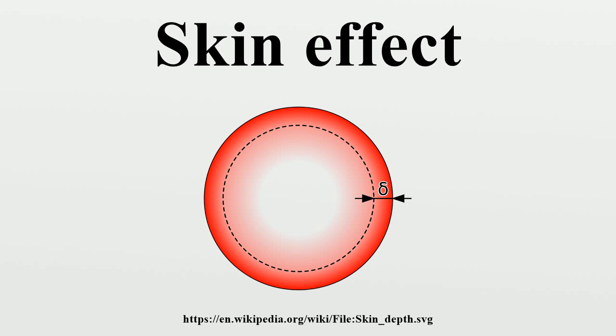The skin effect is due to opposing eddy currents induced by the changing magnetic field resulting from the alternating current. At 60 Hz in copper, the skin depth is about 8.5 mm. At high frequencies the skin depth becomes much smaller. Increased AC resistance due to the skin effect can be mitigated by using specially woven Litz wire. Because the interior of a large conductor carries so little of the current, tubular conductors such as pipe can be used to save weight and cost.